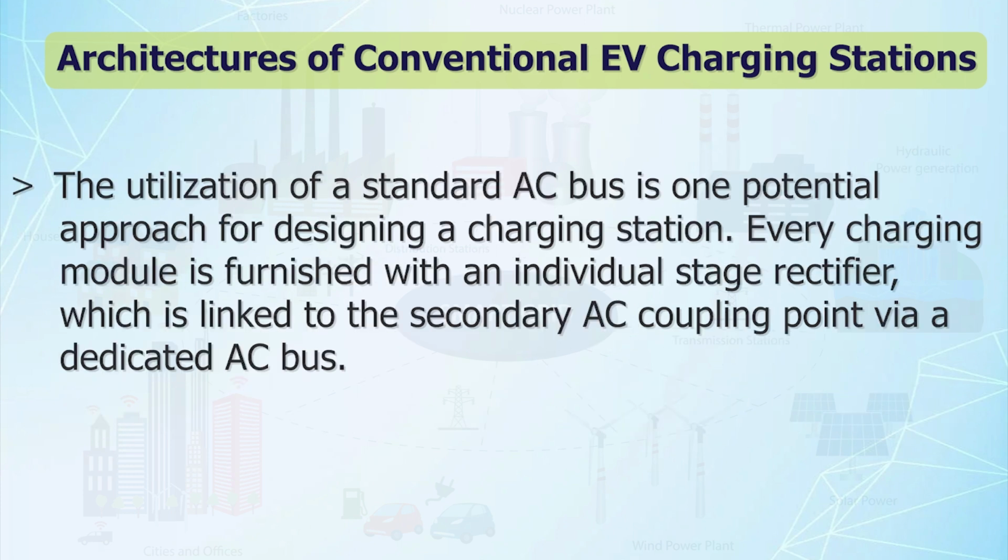Moreover, the utilization of a standard AC bus is one potential approach to design the charging station. Every charging module is furnished with an individual rectifier stage, which is linked to the secondary AC coupling point via a dedicated AC bus.